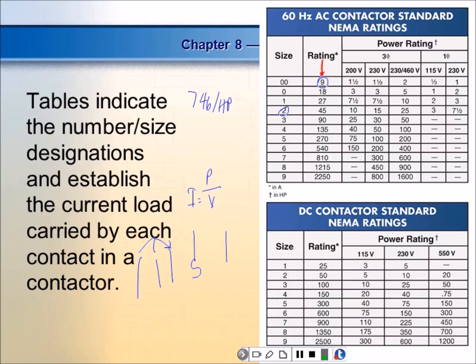First of all, in Europe, or anything that's inside the International Electrotechnical Commission, IEC, their motors are going to be rated in watts. Our motors are rated in what? Horsepower. So you need to learn the two. So going from watts to horsepower, or horsepower to watts, to get a pretty good idea, I would take horsepower times 746.